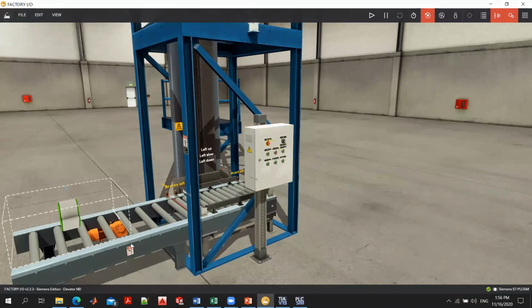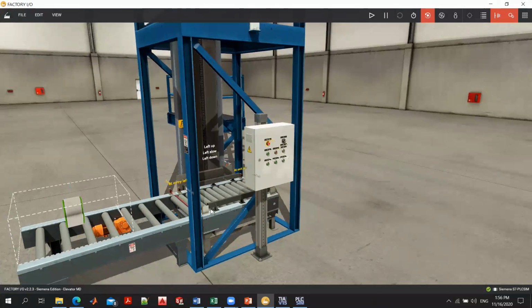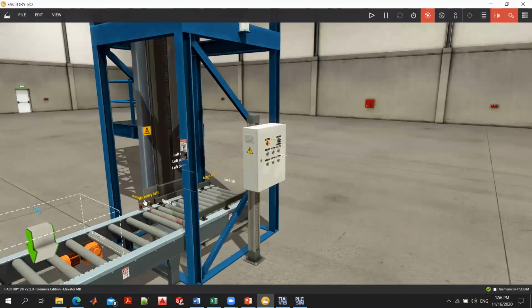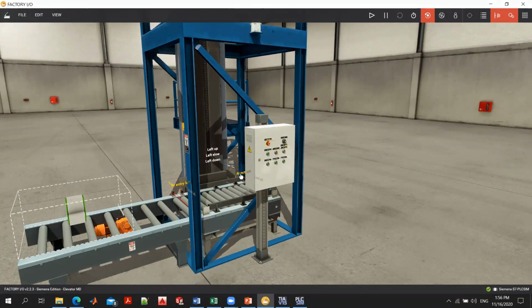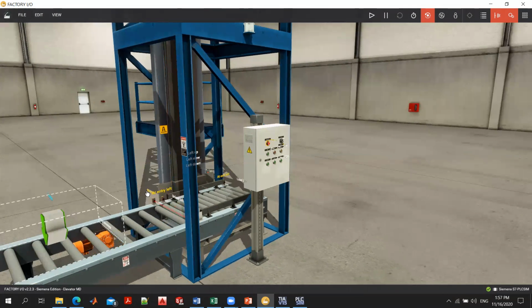First, we have the conveyor input that should stop under some conditions, such as when the loader is not here. Okay, so this is the loader. If it is not at floor 0, the conveyor should stop when it reaches the at entry sensor. We have another condition: when the loader is loaded and the sensor at exit left detects an object. So the conveyor will stop if there is an object at the entry.